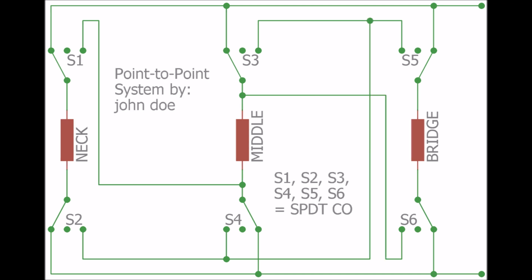After verifying and testing all our solution options, the result is that all the circuits derived from our corrections work and function as drawn, as switch systems that can connect the 3 pickups in 17 unique parallel, series, and compound pickup connection combinations. It must be pointed out that this set of solution procedures applies only to this particular base circuit design, and it is not a universal solution for all designs.